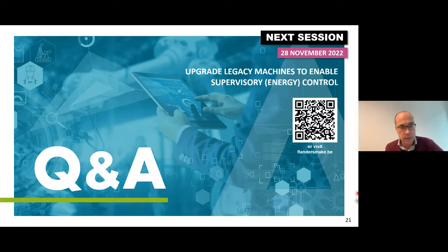And I guess that Edward can also talk on that on his case. Yeah, so indeed, on the cases that we ran, so the SCARA and the Delta robot, we also used the execution time actually as a constraint. So the time we took to move from A to B was actually the same in the conventional and in the optimized approach. We really exploit, let's say, other degrees of freedom than making the whole process slower. And get these kind of quite interesting gains there.